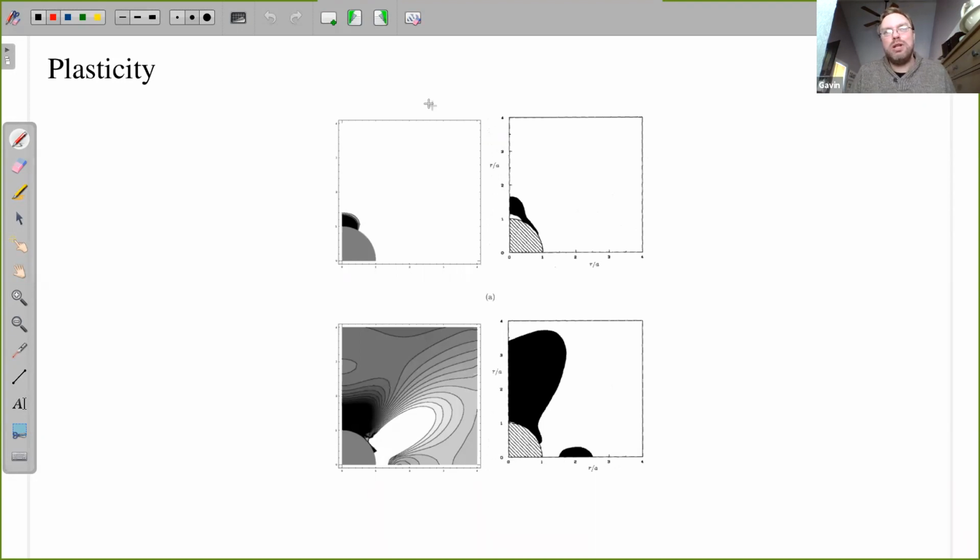And so what you would do is, instead of having those nodes deform elastically, now you say, we recognize that the elasticity is going to get less, but we're going to have more deformation. So you put internal forces in there just to sort of shore that up, and then you reduce the elastic modulus to give you the correct sort of behavior.